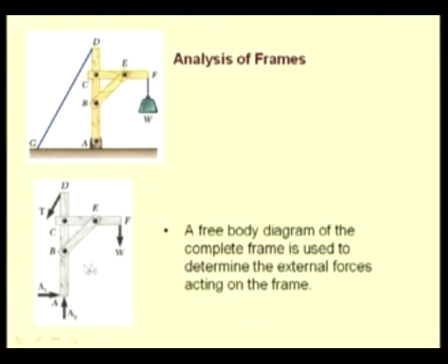For the equilibrium of this rigid structure, the sum of the forces has to be 0 and the sum of the moments has to be 0, and this condition results in 3 equations which can be solved to determine 3 unknowns. So, here we have 3 unknowns, that is AX and AY, the two components of reaction at A, and the magnitude of the tension T. So, the problem is statically determinate and one can determine these forces.